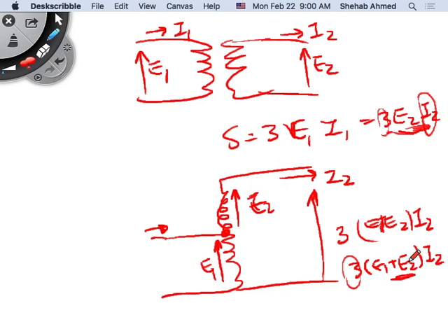You're not increasing the power of your generator. I mean, no. Maybe that's because it's confusing. Yeah, no. Whatever you're generating is whatever you're generating. I'm talking about transformer infrastructure. So for generation, you cannot. Wherever the loads require peak power is whatever you need to generate. But I'm talking about the throughput. Instead of putting two transformers in parallel to carry the load, you will need one, for example. Right?